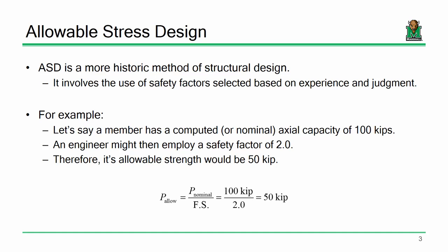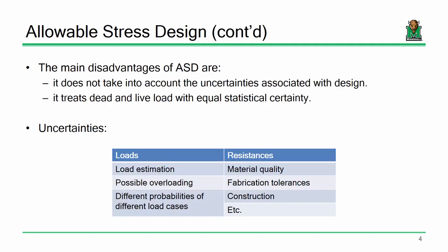It's pretty tough to come up with a calibrated design philosophy for something like geotech. Anybody who's got any experience in geotech will tell you that if you drill right here and drill over there, you're going to get different soil properties. It's going to happen, okay? So you're going to have to, I don't want to say wing it, but at some point you've got to just go with a factor of safety that makes sense, okay? And there's judgment that goes into that. Now, fortunately for us, in structural engineering we can classify those uncertainties pretty well.